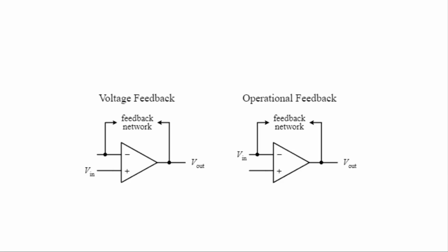Now more on negative feedback. Negative feedback is the wiring technique where the output voltage is sent back to the inverting terminal. This voltage can be sent back through a resistor, capacitor, or complex circuit, or can simply be sent back through a wire, and it changes the formula a little bit. There's really only one formula you need to know for negative feedback circuits, and it looks a lot like the previous one, V out equals gain times the inputs. There is, however, the V negative or inverting input in the formula you must consider.